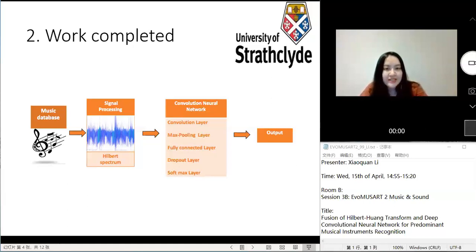The main difference is that the Hilbert-Huang transform can be thought of as a phase shift converter, and the traditional Fourier analysis uses a series of sine basis functions to perform operations on signals. However, the resulting Fourier spectrogram is only the weighted mean of the frequencies over a certain period and cannot accurately describe time-frequency change.